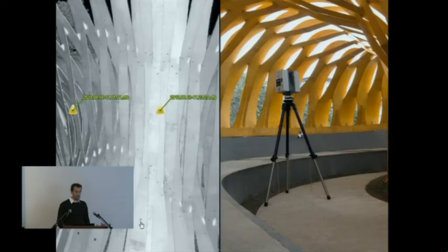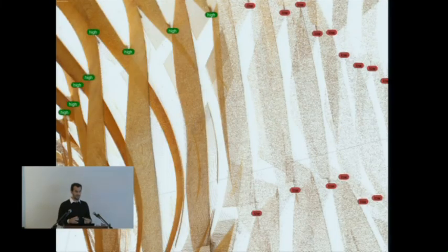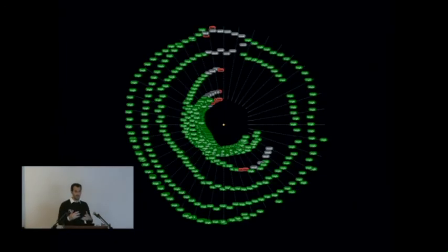And this scan was done by repeatedly digitizing the pavilion with the help of geodesic engineers of the University of Stuttgart using full-scale scanning equipment, which resulted in a huge point cloud, more than 160 million points. But we could write an algorithm that allowed us to extract the critical measure points and overlay them with the computational design model, which in the end showed only minor deviations.